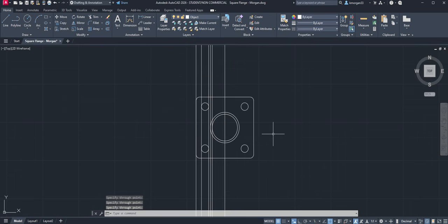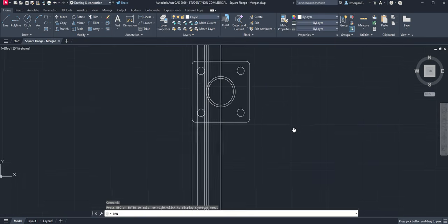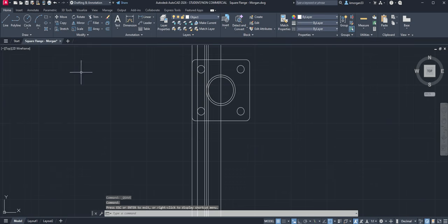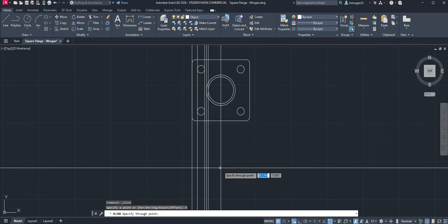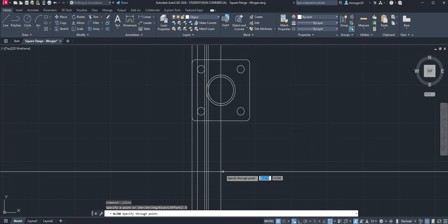Then go ahead and end the X line command by hitting enter on your keyboard, and save it. So save right here. And then next, let's move it up a little bit. I have very limited space right here, so I move it up here and escape out of it, and then I'll do the construction line again. This time we are going to go into the horizontal. And of course you can go around here, when you look at it.